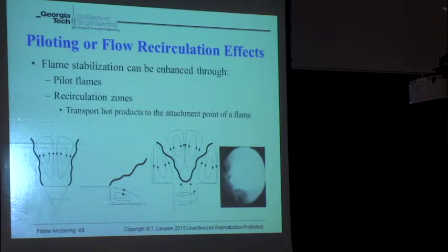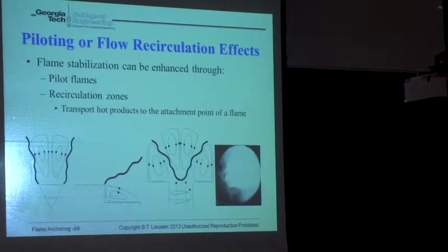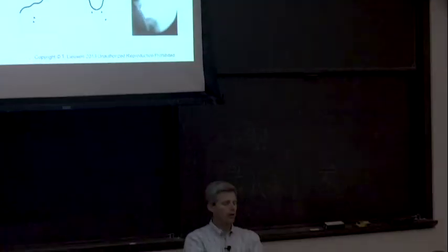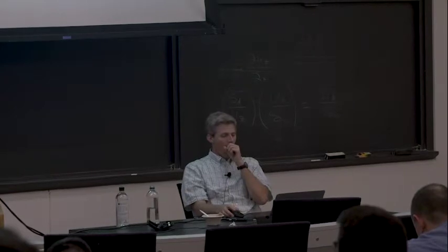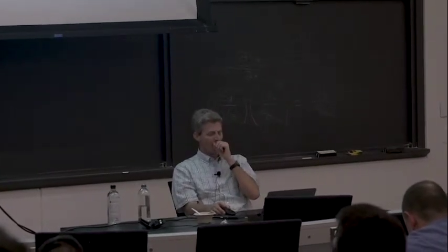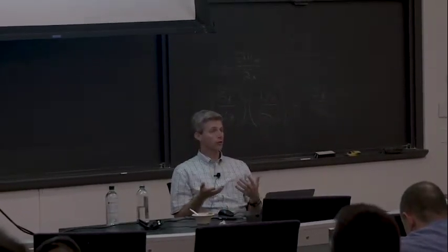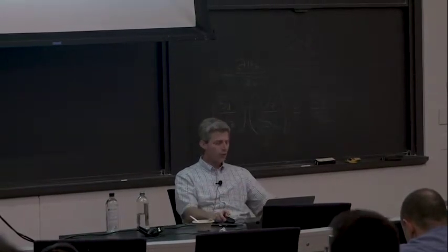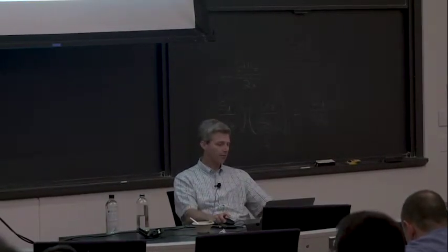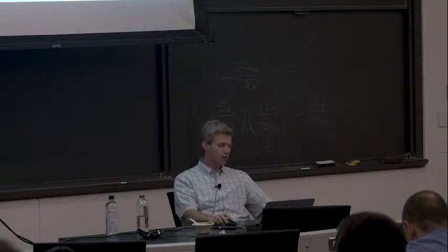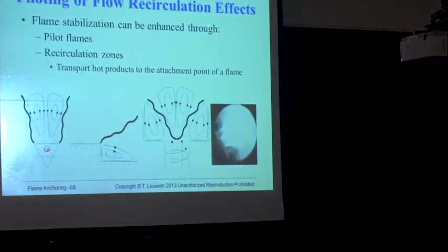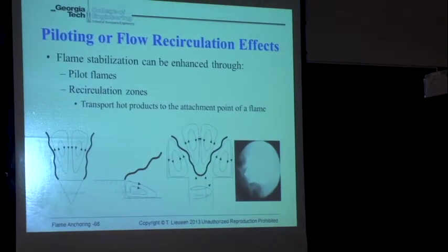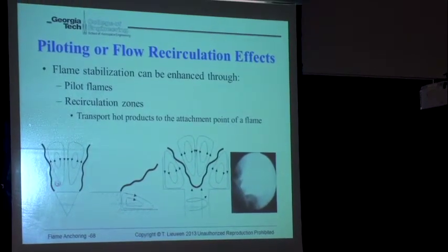Okay. The other thing I want to talk about, another topic, sort of jumping, but on a related topic, is that in addition to flames being stabilized in shear layers, where there's high stretch, almost always there's also recirculating flow at the same time. So for example, if you have a bluff body, the flame is going to sit like this, but you actually have backflow, you have recirculating flow back here. And so what that shows you is what's a canonical problem to model this.